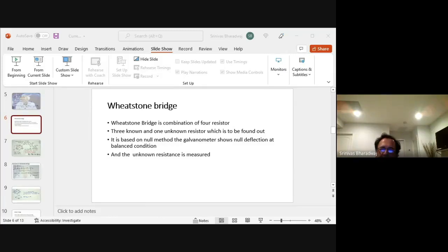Now, you're trying to find the internal resistance of a battery. So that is another application, either the EMF of a cell or the internal resistance of the battery. So the current through AB, when null deflection is obtained through N1, equals V, the voltage, divided by RV, the variable resistor, plus R prime.